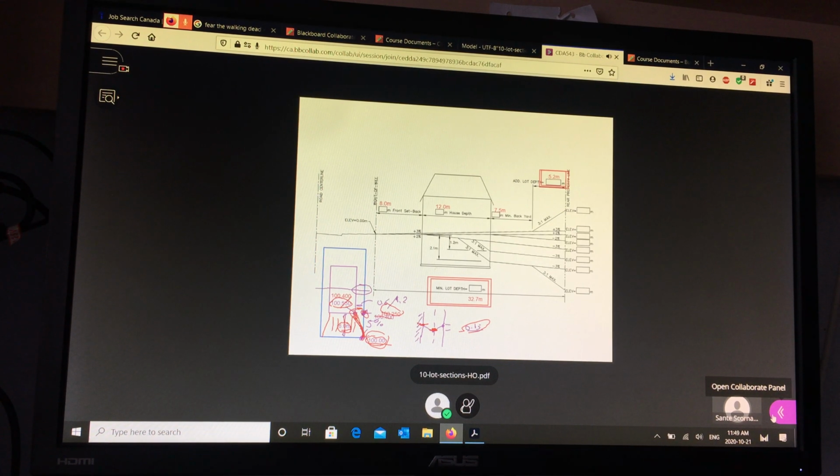Okay, so that's why, even though the standard says 5%, they mean 5% anywhere. Well, if you want to have maximum 5 inside the lot, you can't use 5% on the edge, and this is why. And that's true in the backyard as well. The same idea is present in the backyard. Okay, so that's just a brief explanation as to why I'm not using 5%.